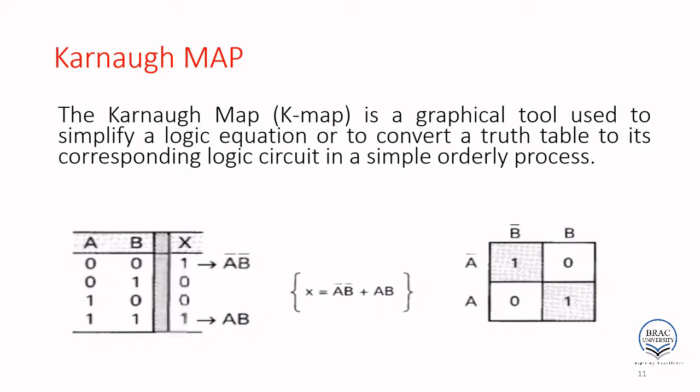So you can write it as A and B this way as well, or you can represent it that way. It says 0 0 is 1, so this is your 0 0, because A prime is 0, B prime is 0, and it says 1 1, so A is 1, B is 1 here, this is high. This is the representation. This is called the K-map, 2 input K-map.